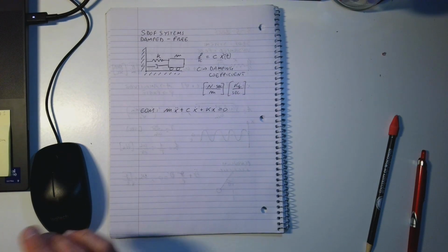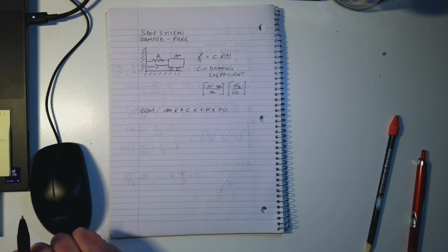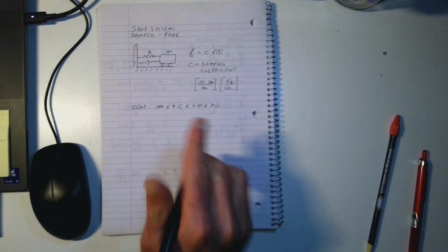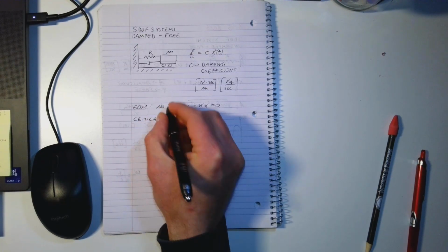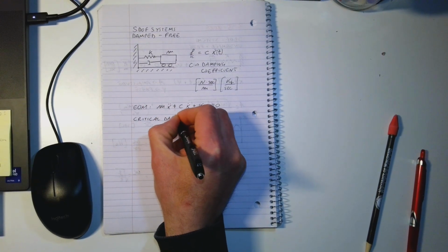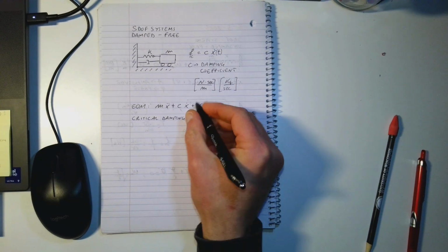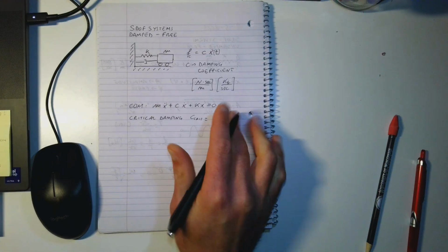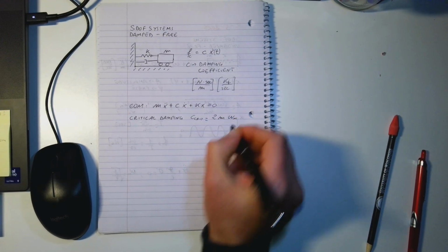In this case we did a little bit of manipulation of this equation, because if you remember we introduced the concept of critical damping and damping ratio. So the critical damping was introduced as 2m omega n.